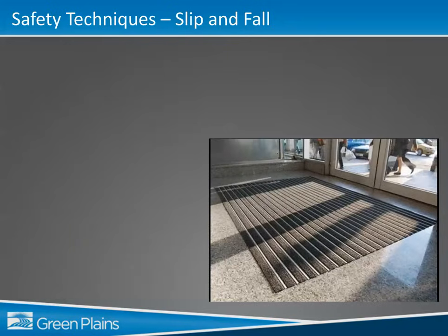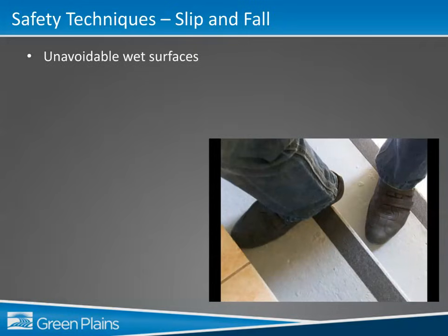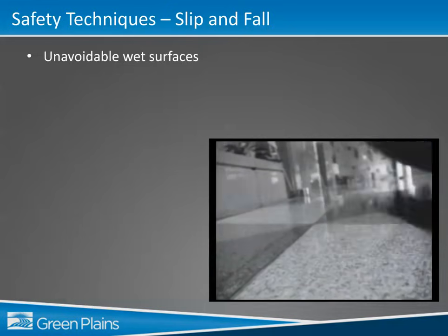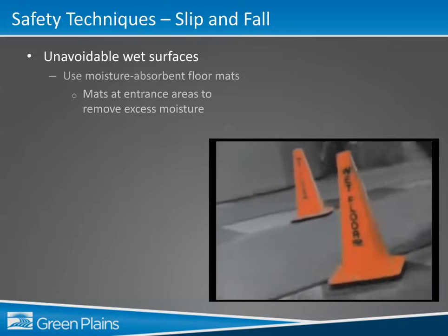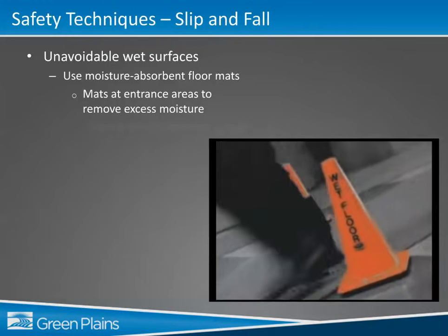In work areas where the walking and working surface is likely to be slippery, floor mats, non-skid strips, or floor coatings should be used. When wet surfaces are unavoidable, use moisture-absorbent mats with beveled edges in entrance areas to remove excess moisture and wetness from the soles of shoes.